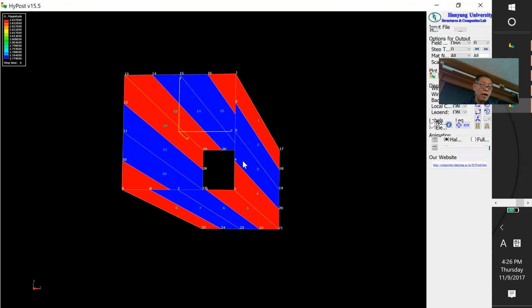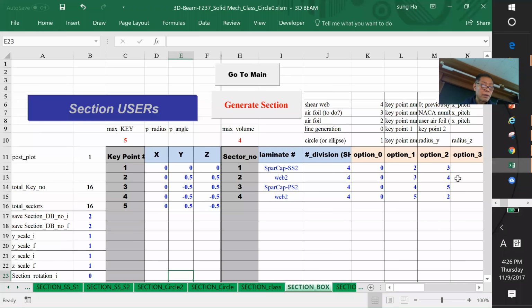So this is how we divide each edge using this number of divisions. The number of divisions is 4. Along this line, we have 1, 2, 3, 4. This way, 1, 2, 3, 4. So it's different. If you choose just 1, 1, 1, 1, yes, as you said, just like that, but it's not very accurate.